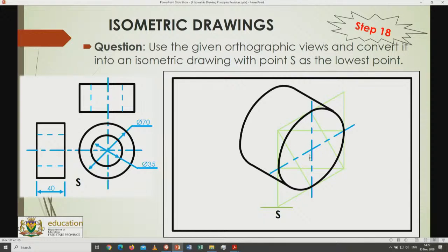Once the center lines are established, I can go 17.5 to either side and upwards and downwards to find my biggest possible block. Apply the principle: opposite sides, closest to each other, bisecting point there, and then from there I can draw the circles in each arc on its own. And of course, I won't see the back circle there, so it's no use going out in this direction. So that is the way you can determine, since this is round, you're going to do the center lines, and you're going to join the center lines with the needle point position of the circle itself.